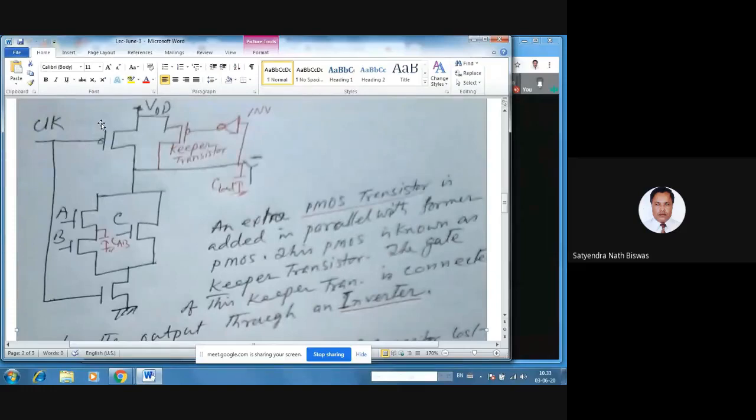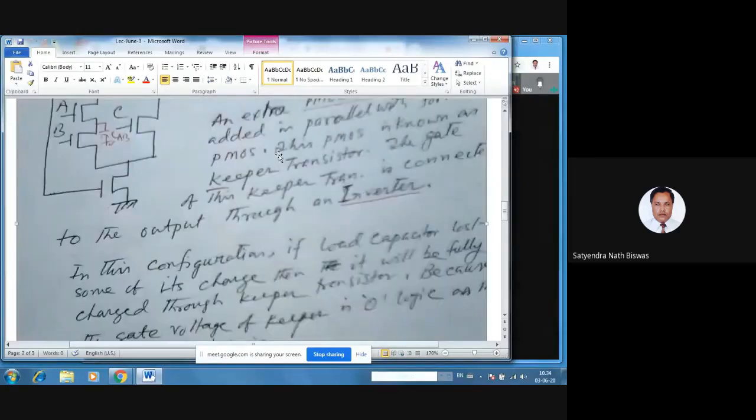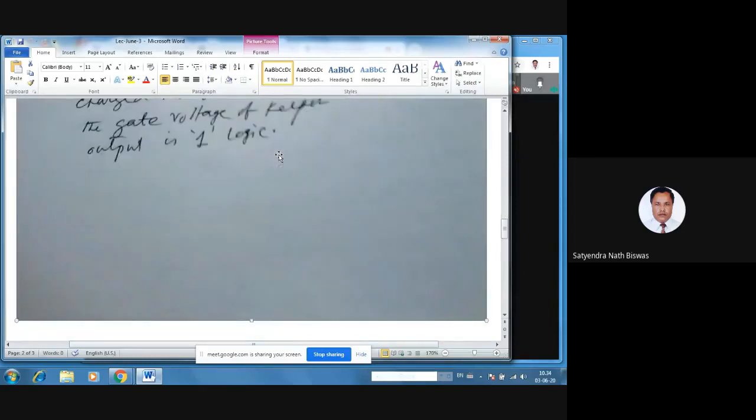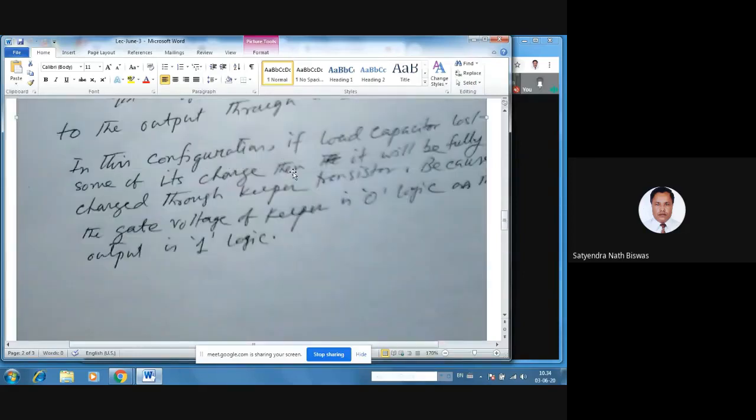Instead of 50 PMOS, we need only 3 PMOS and 1 NMOS, and also 1 NMOS in the footer here at the bottom. So we need 2 NMOS and 3 PMOS instead of 50 PMOS. And so we can save a lot of transistors here. So that's a good thing. It will save space, and also it will save the amount of power required to run those transistors.